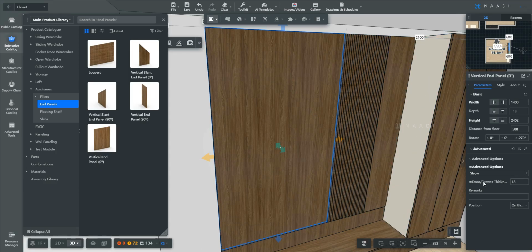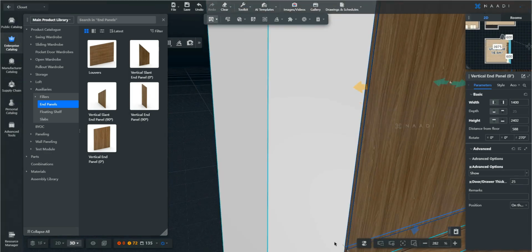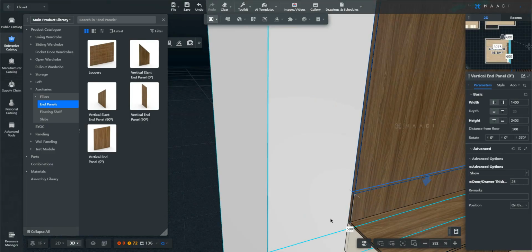And one such technical parameter here is the thickness. Like I said, default will be 18 mm thickness, but according to your requirement, you can decide it. In my case, this needs to be about 25 mm. So I'm just making the thickness as 25 mm. Can you see? As you make the thickness here, it will precisely be updated in the model too.